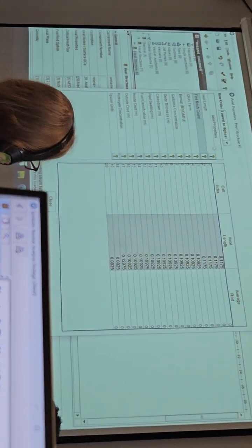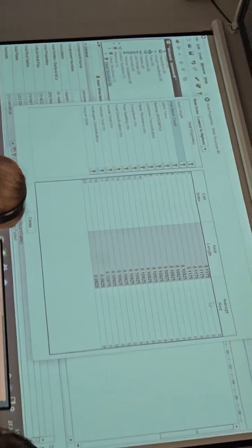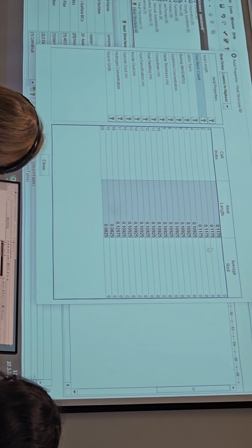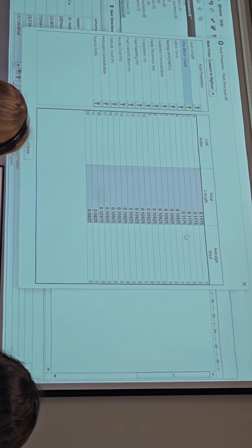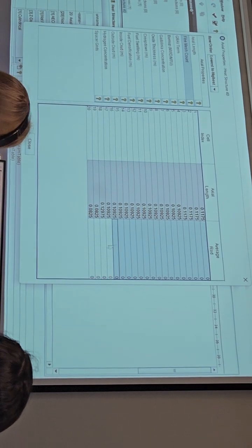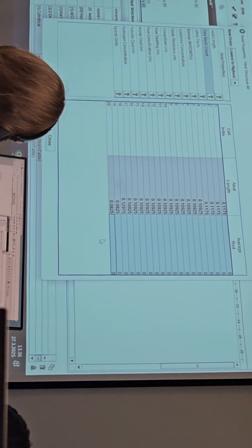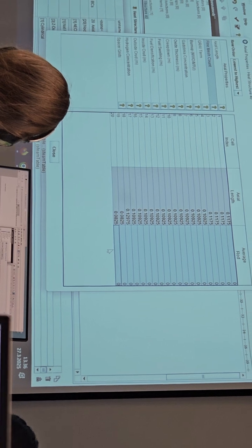One more thing we need to modify here is the fine mesh count. It is the option for each block model. It increases the internal meshing of the fuel rods. We need to define it as 3.